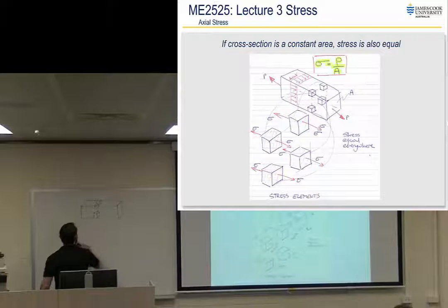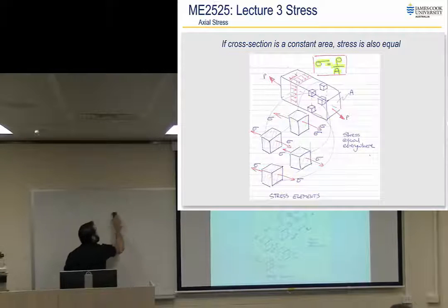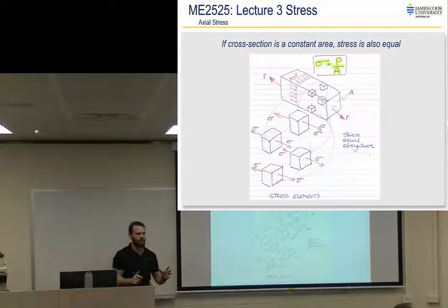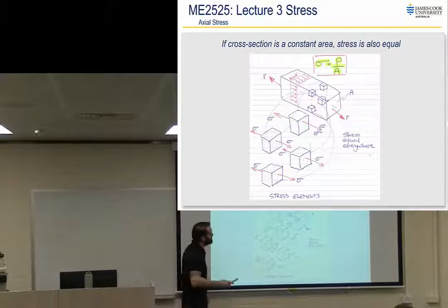So that's one little statement that I'll say right from the very beginning. When you're drawing these things, try and concentrate on your axes. And if you need to go and buy or print some isometric graph paper and use that for your problems, feel free. But you should be able to keep a fairly good, consistent drawing, with the 30-30 straight up and down, if you try hard enough and practice it. So that's the first thing I'll say.